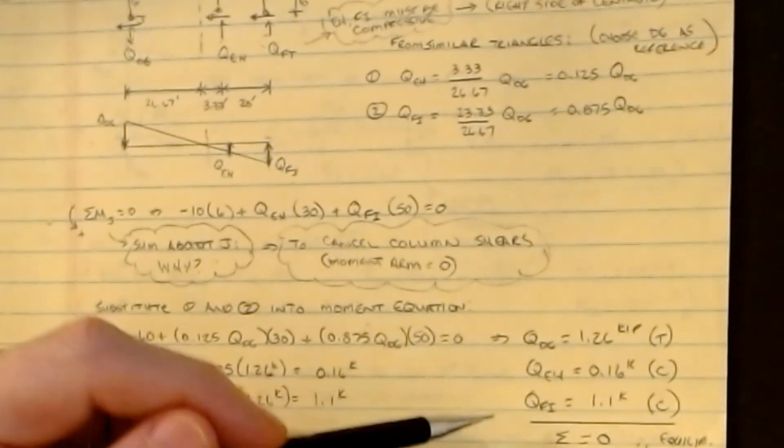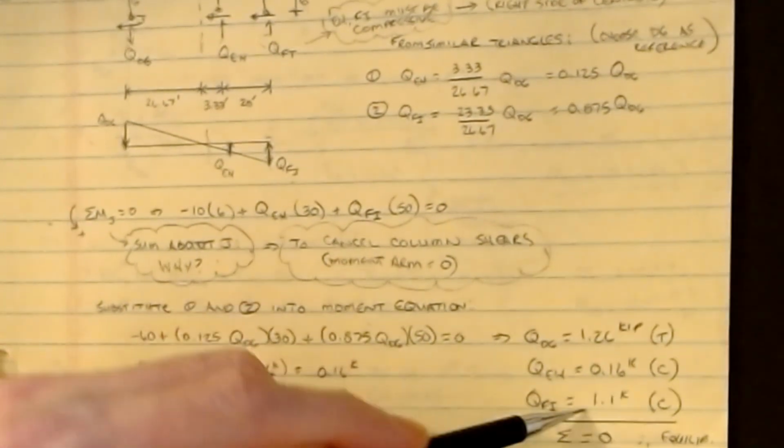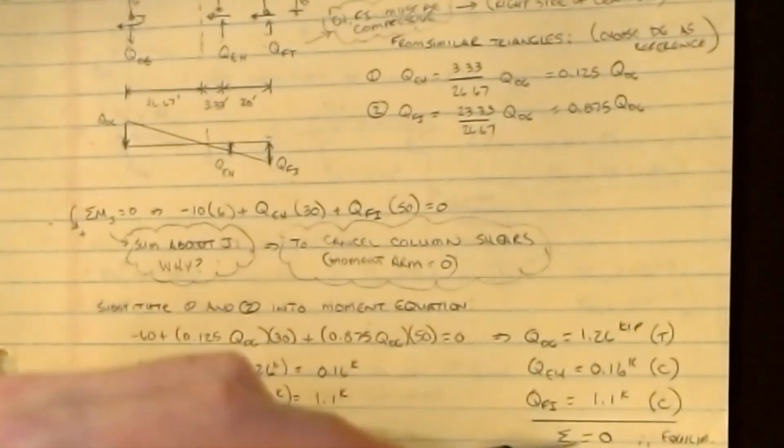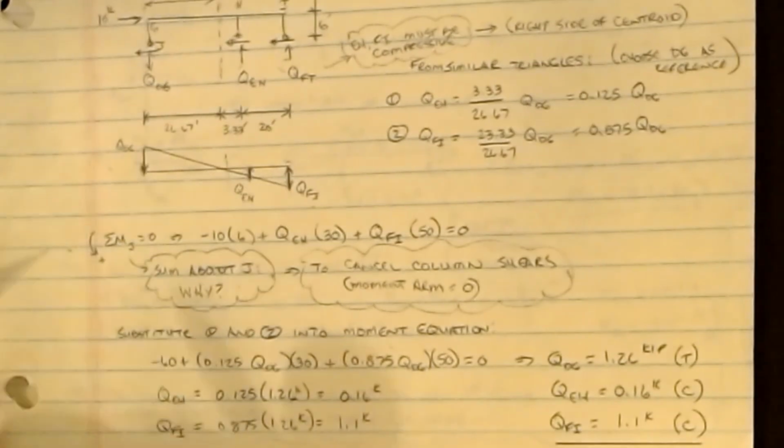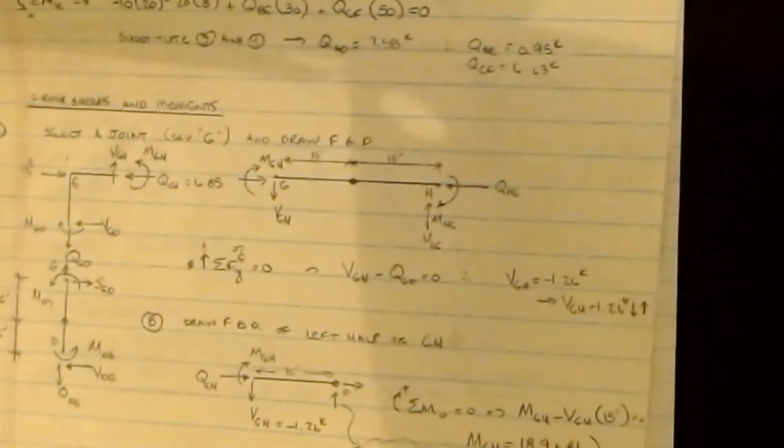Okay, and if you do all of this right, if this is positive and these are negatives, and I sum all those together, you better get 0, because that's the sum of forces in the Y equation. And that's exactly what happens, so we know equilibrium is balanced. But it's very, very easy to do this. Once I have the axial load, then I can go in and start to blow the structure apart into the pieces like we did the last time.